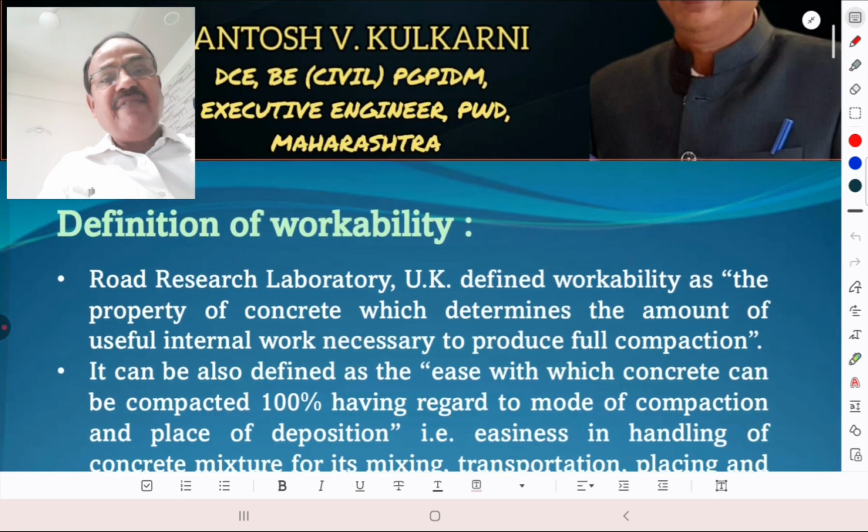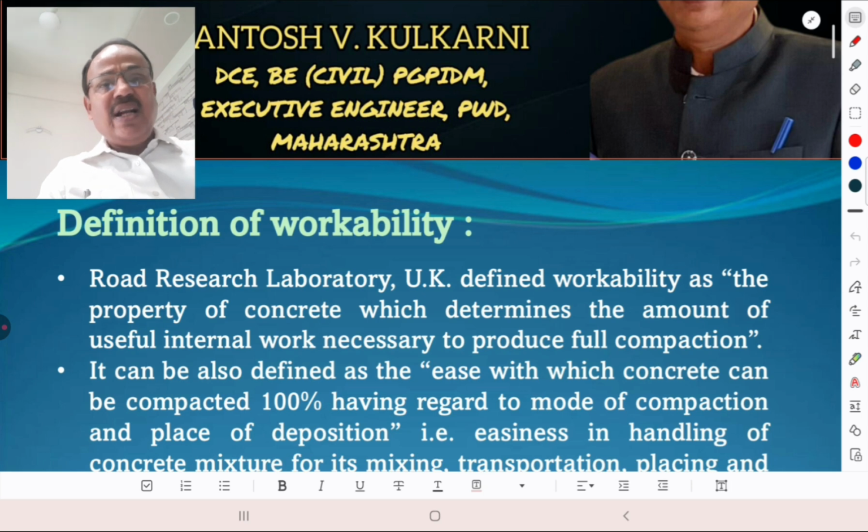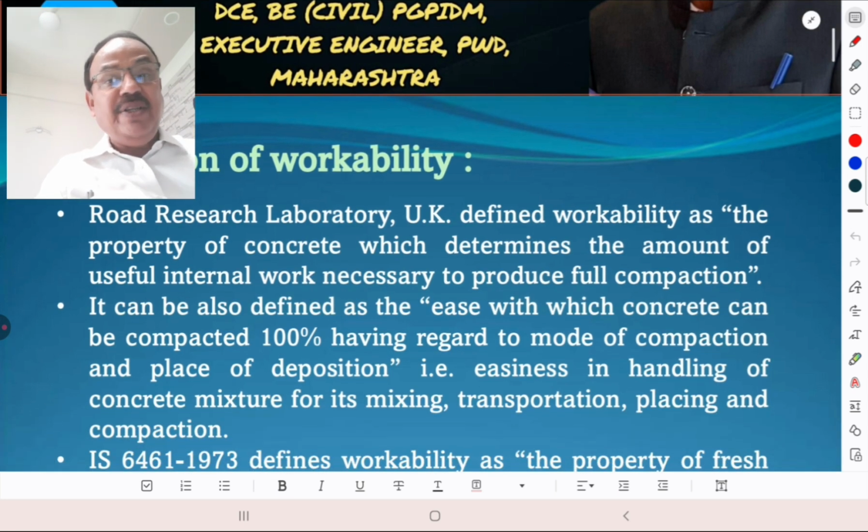First of all, what is the definition of workability? There are different definitions of workability, but according to Road Research Laboratory, UK, workability is defined as the property of the concrete which determines the amount of useful internal work necessary to produce the full compaction. It is a very simple definition. Amount of useful internal work necessary to produce the full compaction.